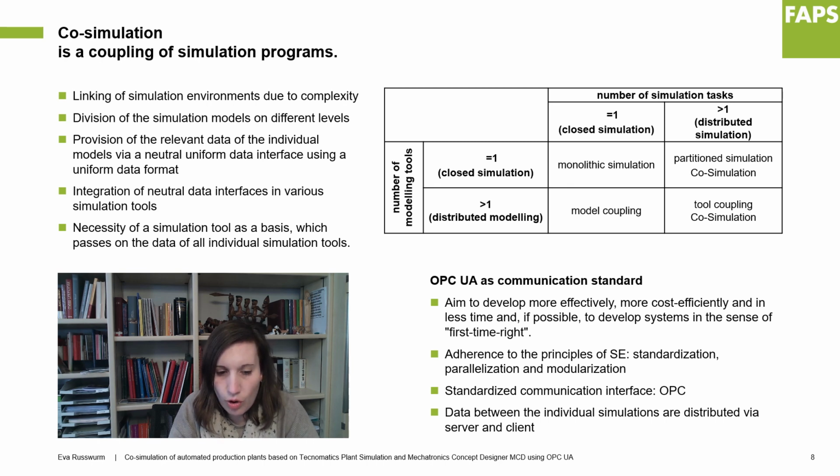It forms the interface between control systems and control level, enabling uniform data exchange regardless of the manufacturer or the tool. So I used an OPC UA server in order to communicate between the different tools which are part of the co-simulation.